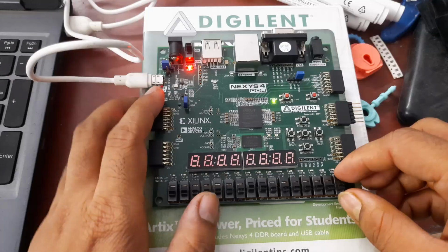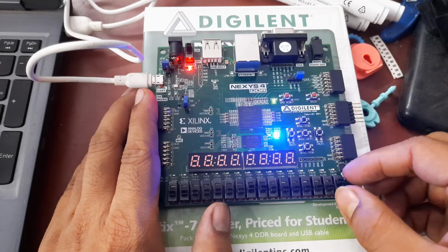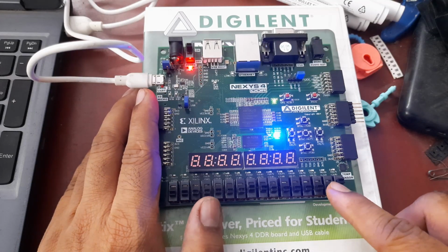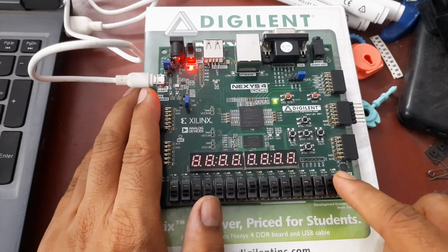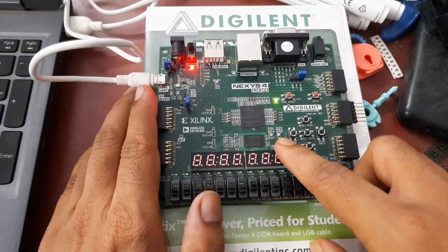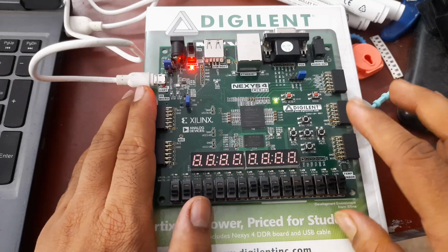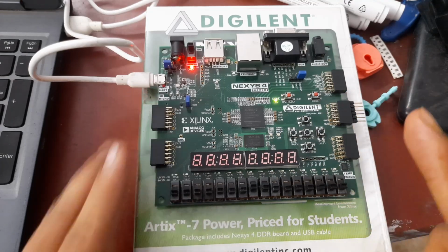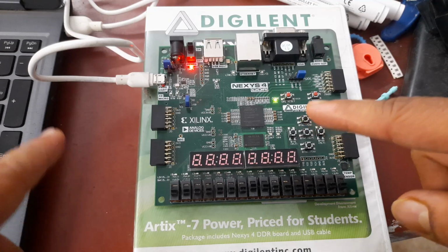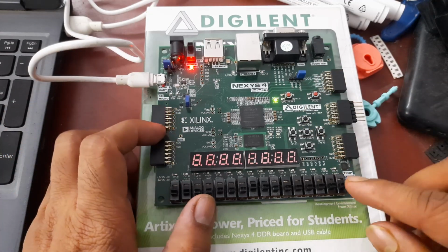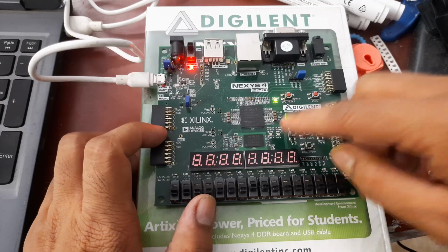This is SR flip-flop, and again in the SR flip-flop, S is equal to 1 and R is equal to 1 is not valid, okay? In that condition I had told you that we have put 0, and you can put anything, it doesn't matter, okay? In JK flip-flop, however, that condition is valid, and I'll put the JK flip-flop code now, and it is programmed. So now this is J and this is K and that is Q.